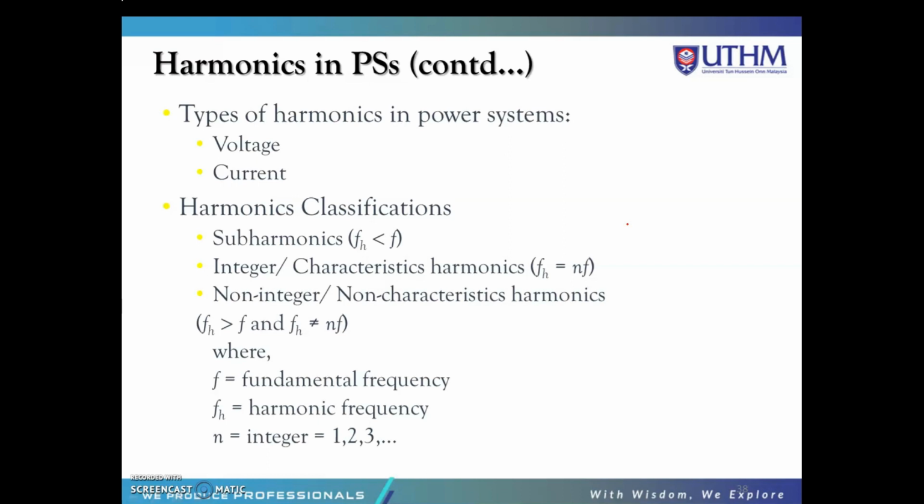Okay, when a nonlinear electrical load such as rectifiers, computers, printers is connected to the system, it withdraws current that is not necessarily sinusoidal at the same frequency as the voltage, and not in phase with the voltage. So the current waveform distortion can be quite complex depending on the type of load and its interaction with other components of the system. Okay, this is what we call current harmonics.